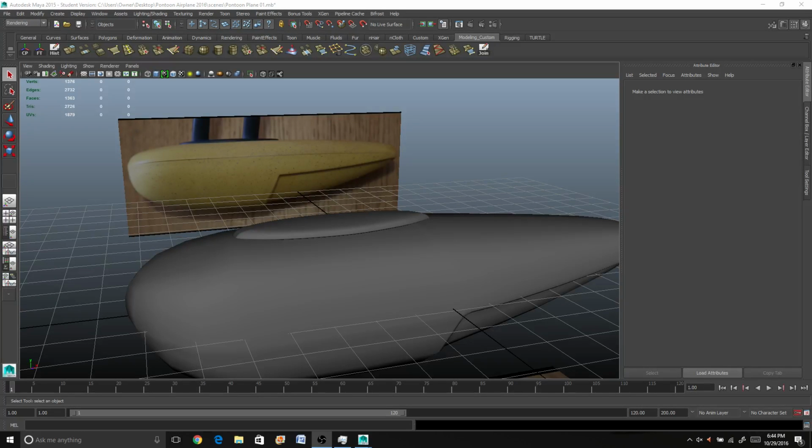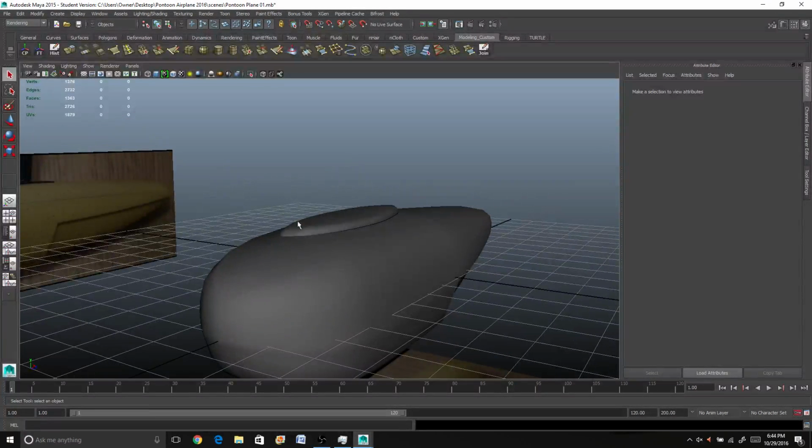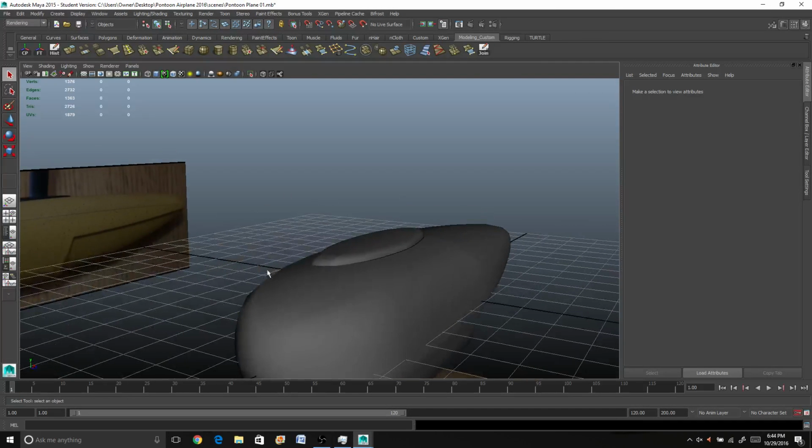This is kind of how we left off. We just got to make our little leg extensions and we'll be done with the pontoon section of this project. So to create our leg sections, we need to actually use a CV curve tool to create this curvature that's going to go along with our legs. Yes, there are easier ways to create this, but this will give you an introduction on how to use the CV curve tool to do extrusions.